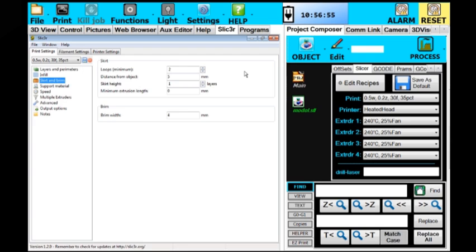It's a final check that we do to make sure that the material is flowing properly, that it's sticking to the bed, and that it doesn't look like it's thicker on one side than the other. That would tell us that the bed's not exactly level. And the brim is an extra bit of material on the first layer only that surrounds your model and gives it extra surface contact so that you have better adhesion to the bed. We recommend using a brim on most models for your thermoplastics.